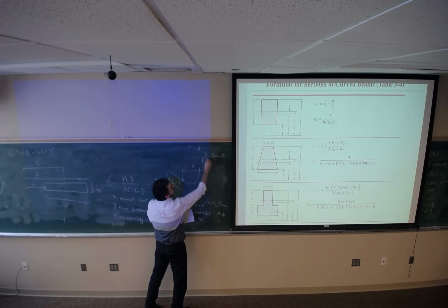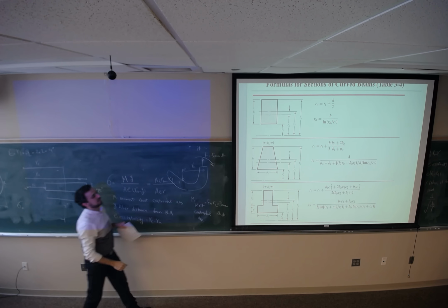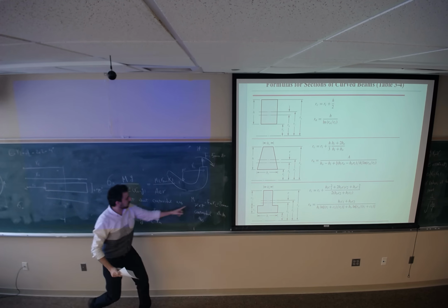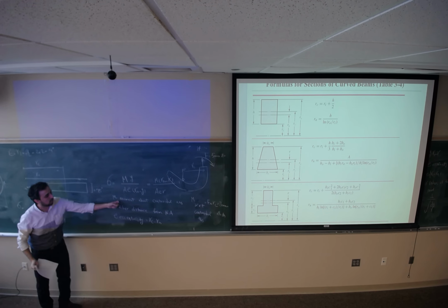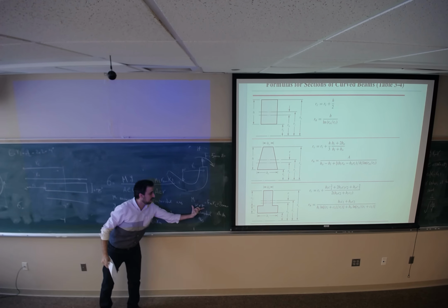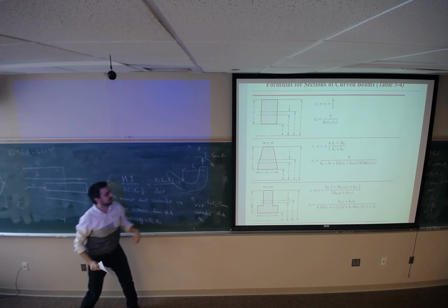The reaction should apply in the opposite direction. Again, this is where I said moment should be calculated about the centroidal axis, not the neutral axis. So for that reason, I calculated M with respect to the centroidal axis.